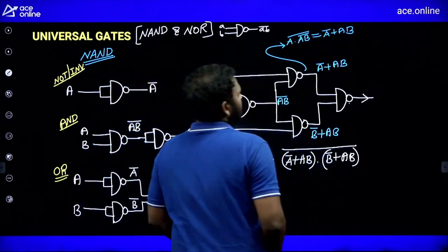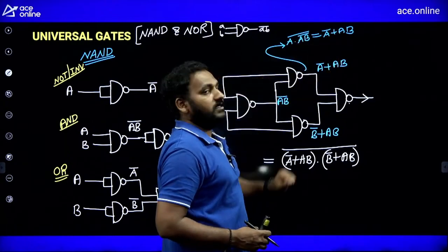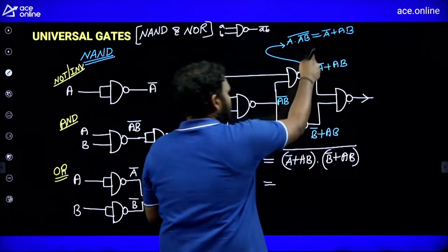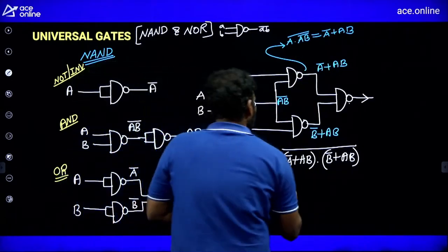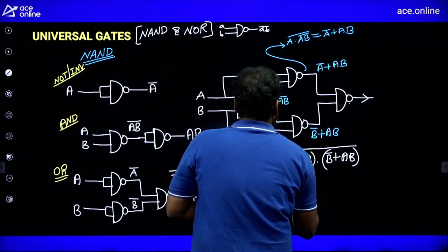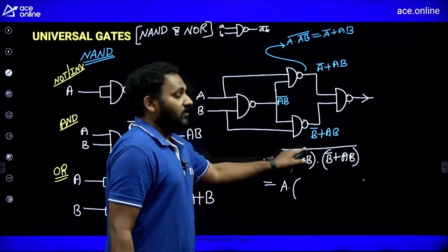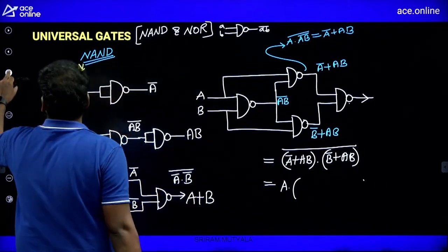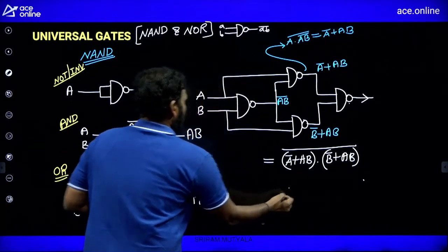So, you see, this is A bar plus AB double bar, that's why I wrote directly AB, okay, please. Now if you apply again similarly one De Morgan's theorem here, you will get A plus, A dot AB whole bar. Or otherwise you can write another step. Due to lack of space, I am trying to skip one step, but no problem, I can adjust it.